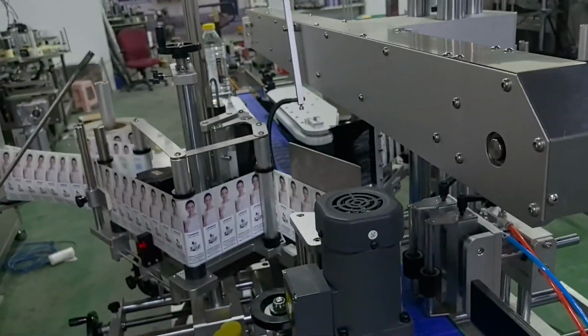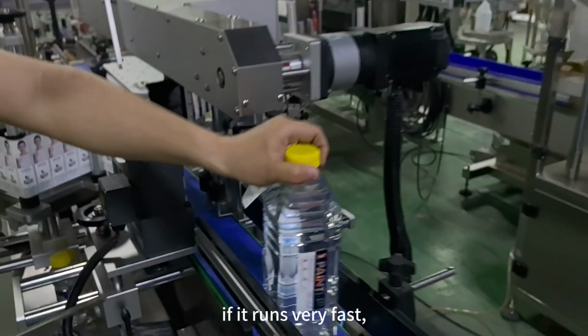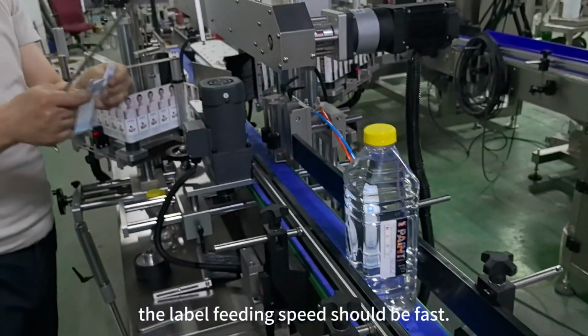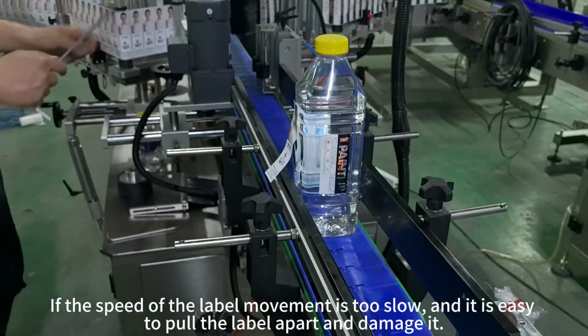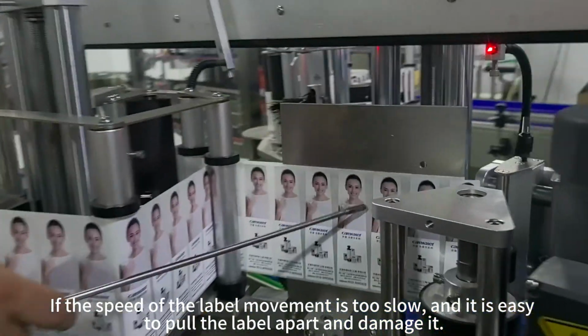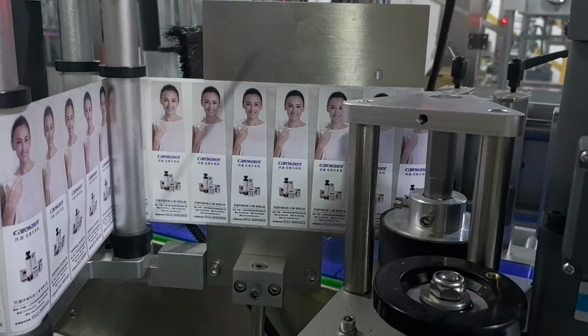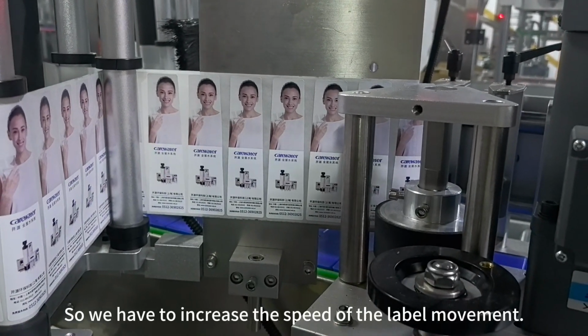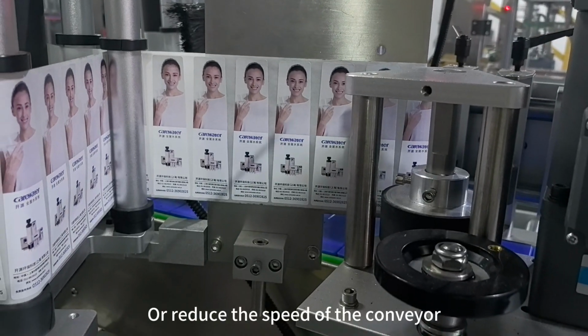That is to say, if my bottle is on the conveyor belt, if it runs very fast, the label feeding speed should be fast. If the speed of the label movement is too slow, it is easy to pull the label apart and damage it. So we have to increase the speed of the label movement, or reduce the speed of the conveyor.